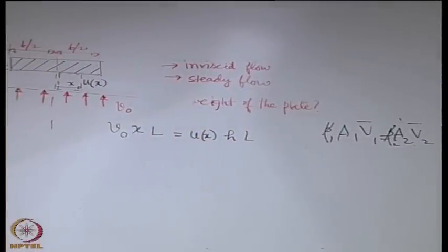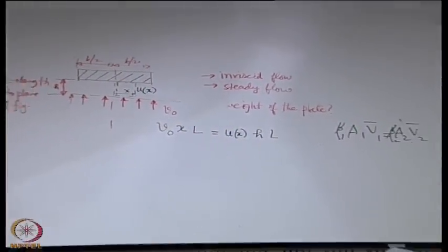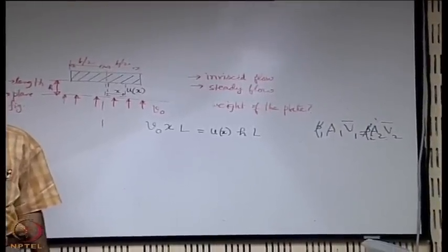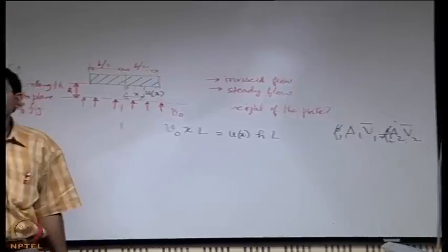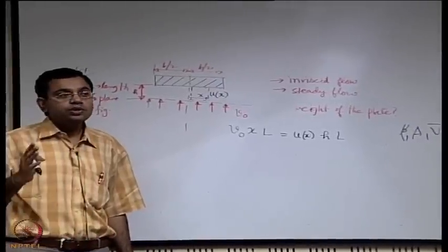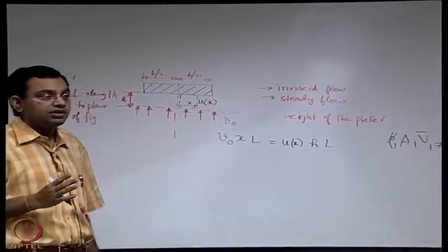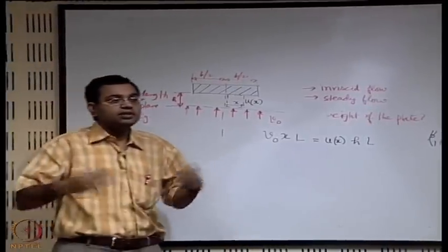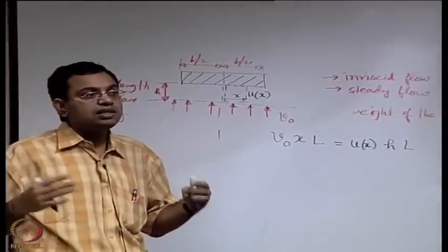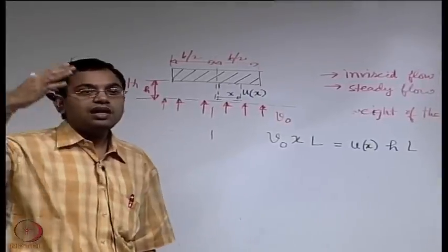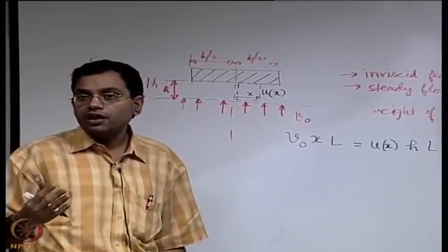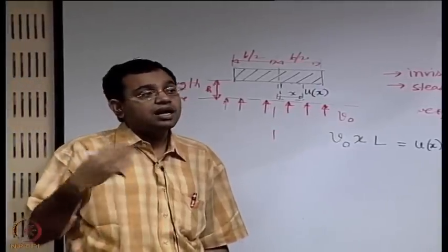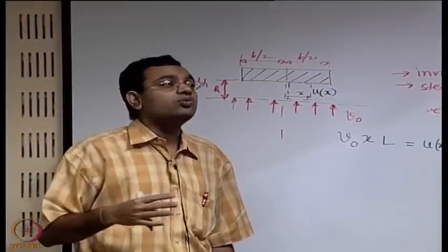And when we say rho equal to constant, the other thing again I am going to hammer on you: keep in mind rho equal to constant is a special case of incompressible flow, but incompressible flow does not require rho to be a constant. Even in some of the best textbooks, this confusion is retained. You will see assumptions written as incompressible flow, but incompressible flow can be handled without requiring rho to be a constant.